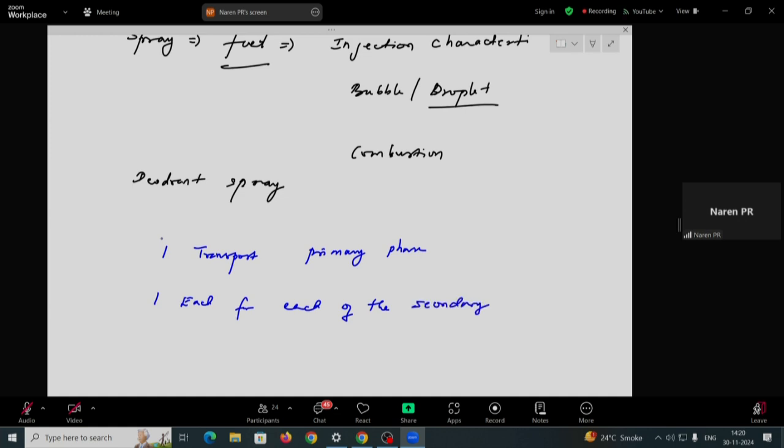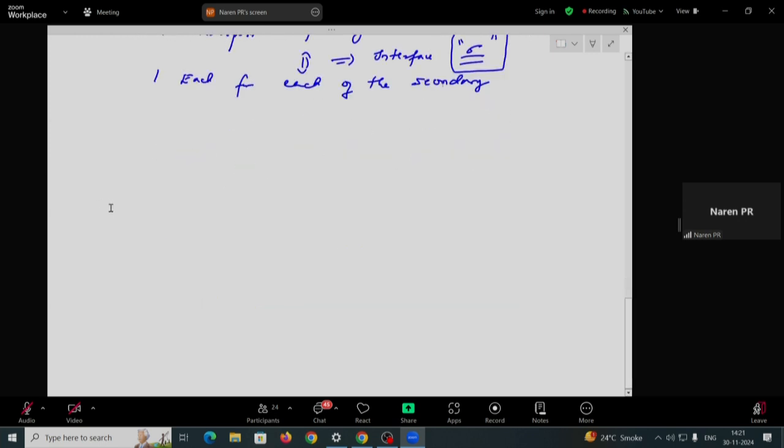This is essentially the same equation that you have seen as Navier-Stokes, but the number of equations is more, and the interface is coupled by the surface tension force, because it is essentially the surface tension that helps you track the interface. So the two phases are coupled through the interface momentum transfer, and one of the key parts in that interface momentum transfer is actually the surface tension of one phase in another.